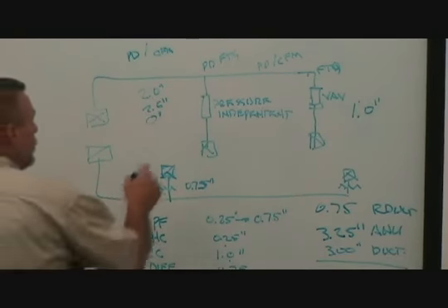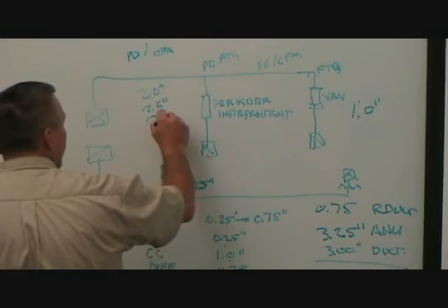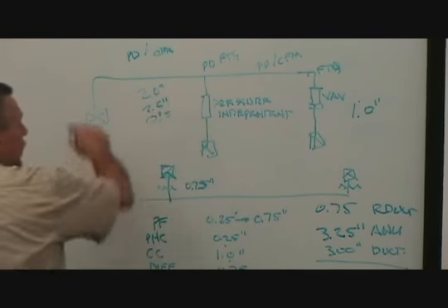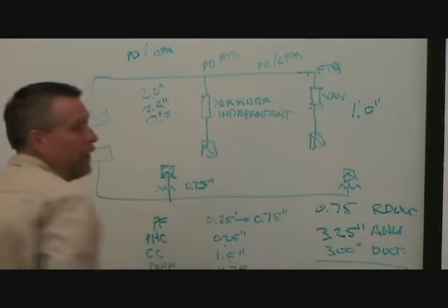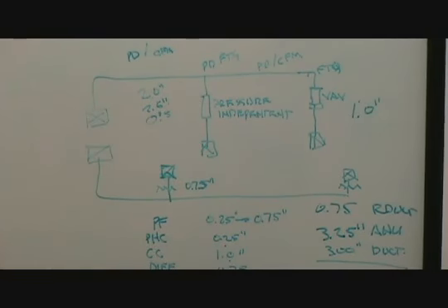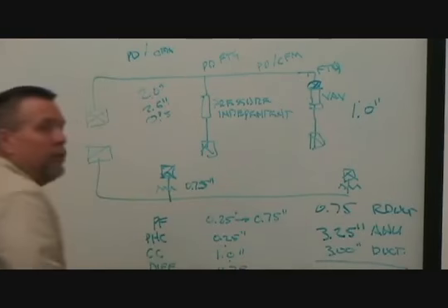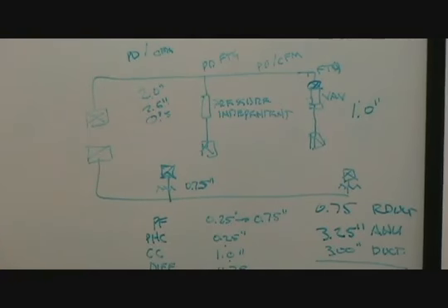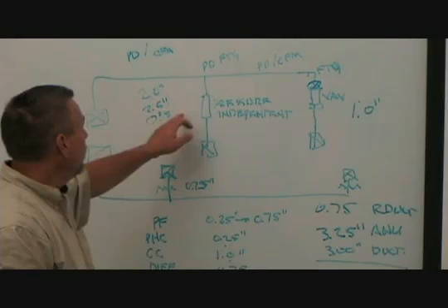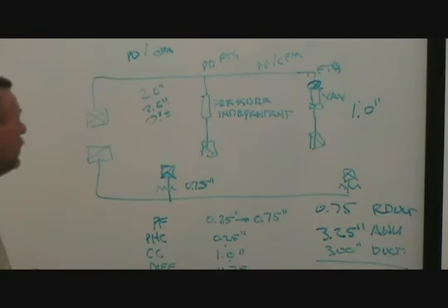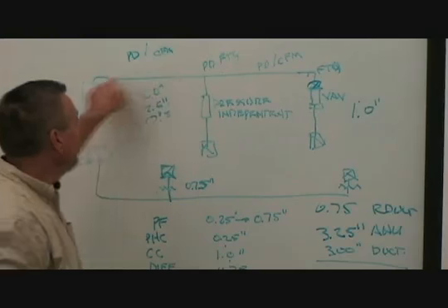They're never going to close, so this might range from 1/2 inch up to 2.5 inches in pressure. These boxes don't really care what the pressure is because at this cross flow sensor right here, I'm measuring velocity and pressure and converting it to CFM. So I always know what CFM is as long as I've got at least enough pressure to measure it. So this is called a pressure independent system.